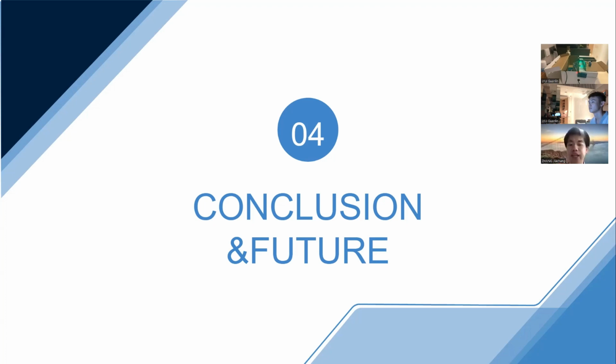Lastly, I think we should also consider the limitation of the infrared sensors if we want to put it into real-case application. For the infrared sensors, there is some interference between different sensors, and people from outside the entrance system may also be detected. So some hardware or software side should be improved. So these are the improvements that can be made.